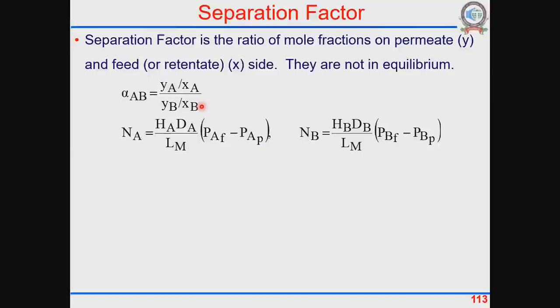So remember we had looked at separation of two different molecules, two different solutes, based on their partitioning or based on their dissociation. When we had done dissociation extraction and liquid-liquid extraction simultaneously, we have defined separation factors. This is not like vapor-liquid equilibrium, where the relative volatility is defined as alpha and these are at equilibrium. This is not an equilibrium operation. It is just on the two sides of the membrane. Y is the permeate side, X is the feed or retentate side.